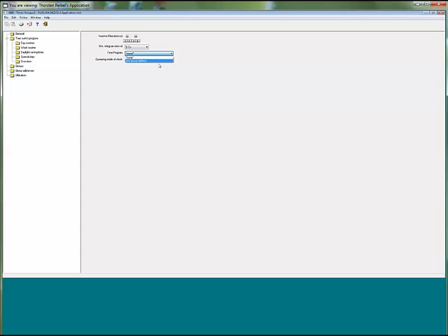The time program can be also activated, deactivated, if you want, completely deactivated at any time, via a telegram. The operating mode of the clock can be internal. There's an internal clock inside. You have to adjust it only once. Or as already mentioned, you can also use the slave function, means you receive date and time from any other clock, or you use a master function. Then you send out the telegram of date and time on the bus to synchronize anybody else. Both are possible. And if you decide internal, then you can go here and set date and time directly here.